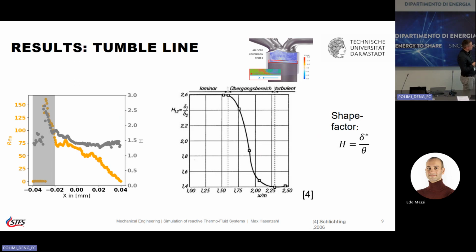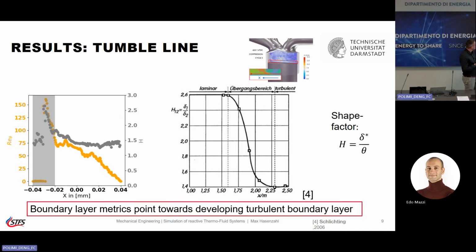So in the turbulent region, you usually have fairly low values of this H factor, and you can see even at the attachment point, even at really low Reynolds numbers, the shape factor would suggest that this is already turbulent. So you have a developing boundary layer that's already turbulent, and it's maybe akin to bypass transition in turbomachinery, and quite an interesting effect.